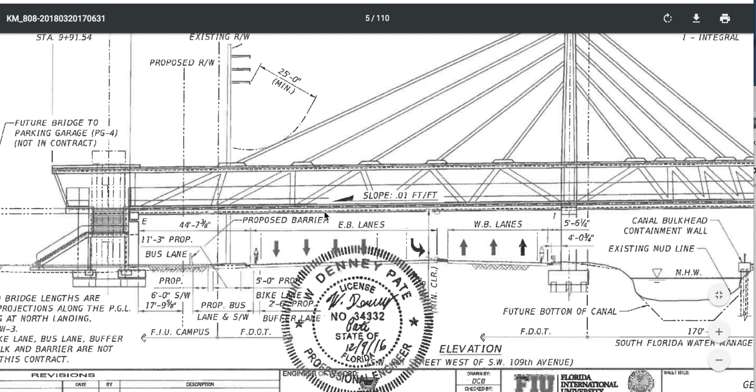So if this deflects down any amount, I state any amount, because this is flat. He has no design here that shows a curvature in it. This is shown as plumb and flat. This is shown as level and flat. It's actually plumb over here in the design. There's a slope for handicap reasons and water runoff, but that's the maximum slope. So I state this can have no deflection in it.